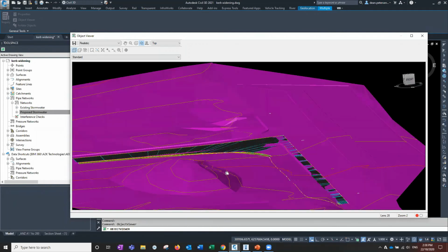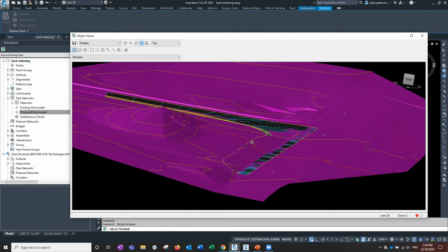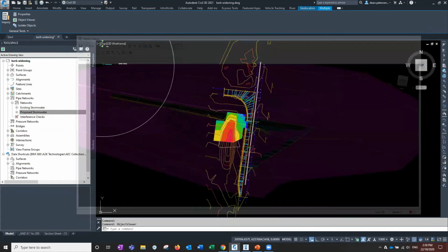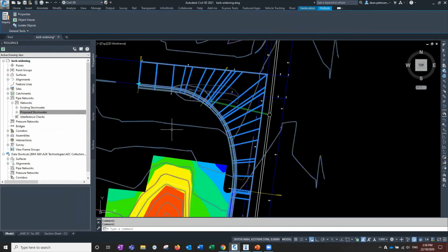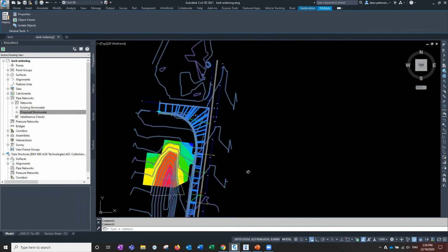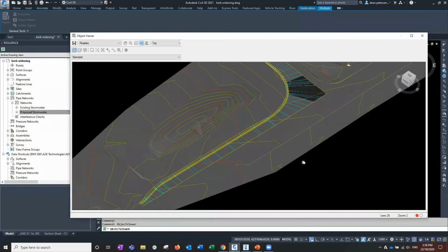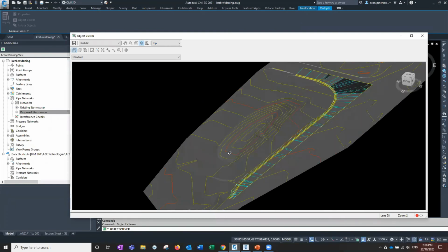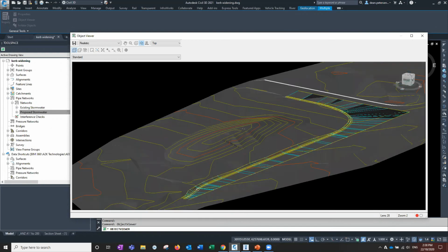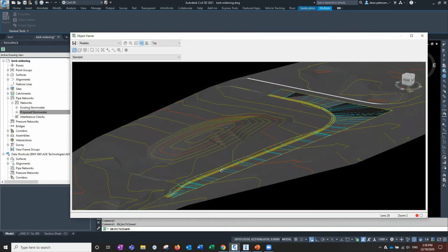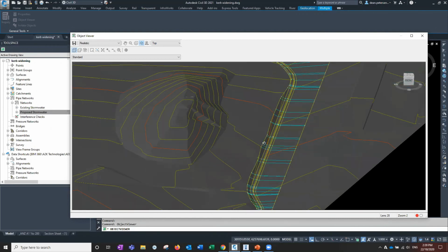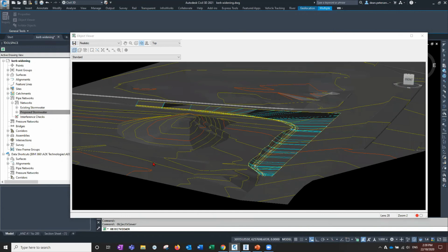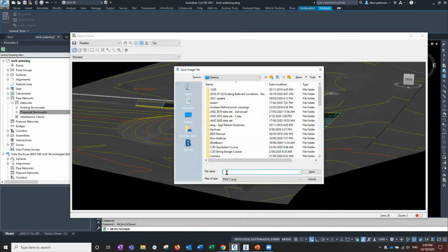Now what we also might want to do, because we're obviously underground here under the EG, we could actually change that surface. So if we close out and we pick our corridor and we pick out design surface instead, that can be useful, in that we're now seeing the top surface level of that. And we can see where the corridor demarcates the changes in the surface, because we don't have the other one over the top, the existing. So that's another nice way to do it, another save there, and call it top.